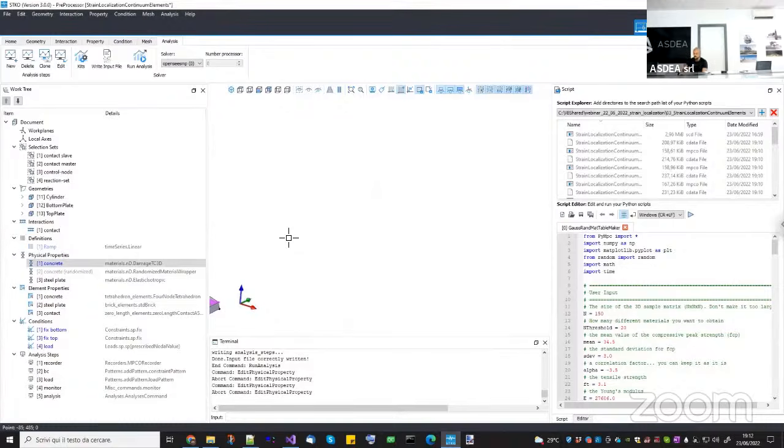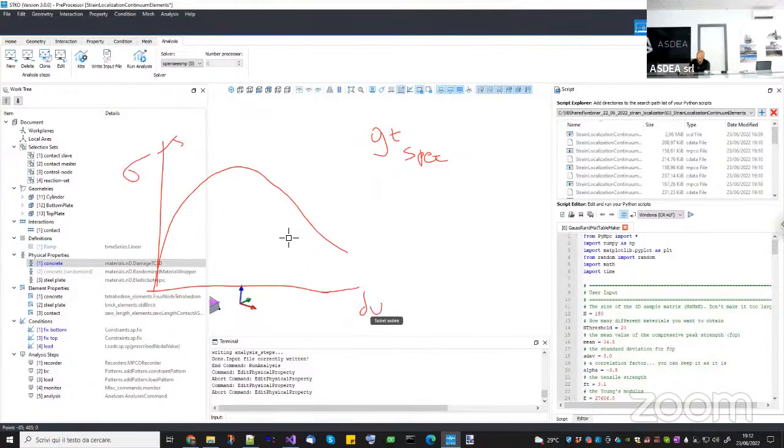So in all the examples that I've done before, I assume that you have the real fracture energy. In this case, when you have a specific fracture energy from an experiment or from a national code, it is the same thing in this case. What they gave you is the GT, which was specific to the specimen. Okay. What does it mean? It means that they measure something like this. They measure a stress versus displacement jump.